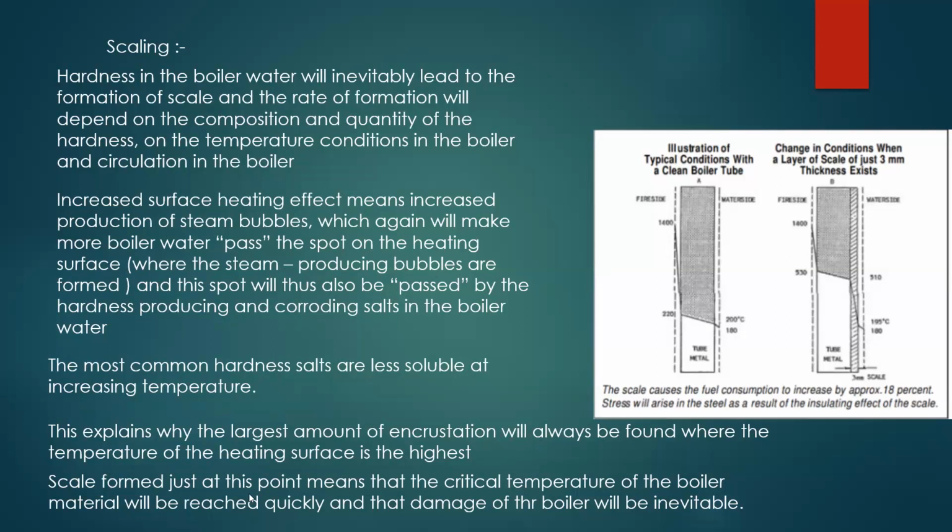Scale forming just at this point means that the critical temperature of the boiler material will be reached quickly, and damage to the boiler tubes or boiler shell will be inevitable.